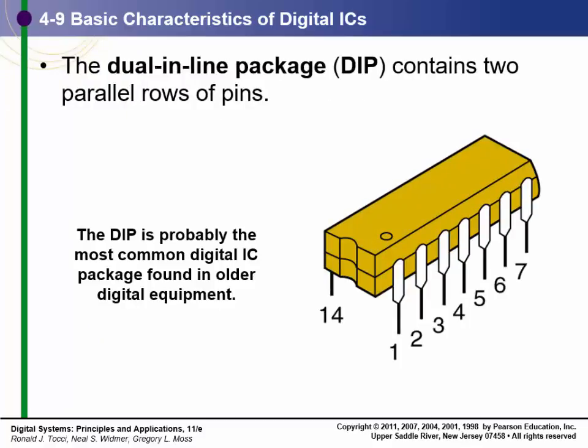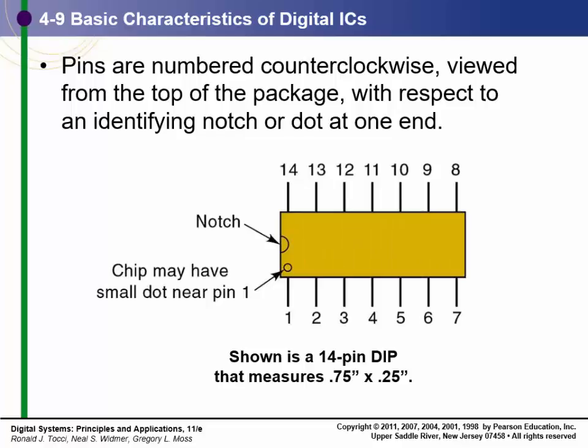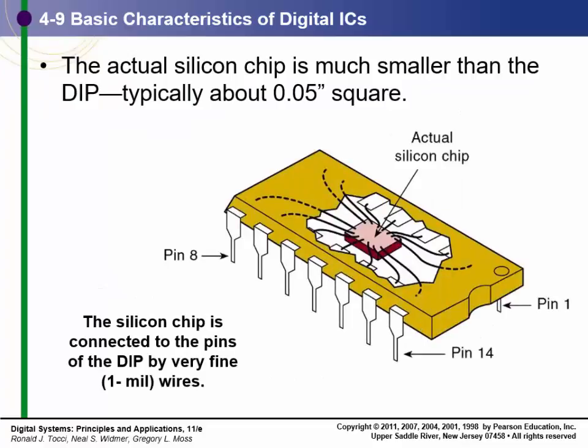But the concept is that we get into the manufacturing process, which I'm not going to get into. This is what this book typically talks about: traditional TTL logic, where we teach digital electronics using SSI chips, and they're 14-pin chips. We're not going to see any of those, so I'm going to kind of go through. This is the common numbering system. It goes around like this, pin 1 to pin 14. Pins 7 and 14 are typically ground and VCC.